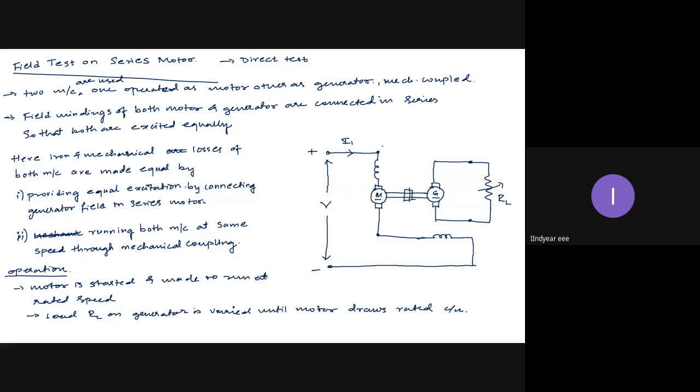So let me take the motor voltage by connecting a voltmeter across the motor, and let this be V1. Now V1 is the motor voltage, whereas V is the supply voltage, which also includes the voltage of the generator field. Then the generator current, let it be I2, and the generator voltage, let it be V2. Let me take the computations.